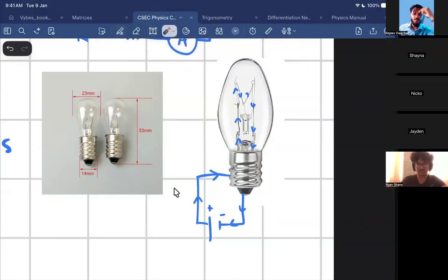This is effectively a short circuit, because it's just wire. You're connecting one side of the battery to the other side directly. Let me explain what happens. Anytime you short a battery, you're creating large amounts of heat. Why? Because of the maximum current flowing.